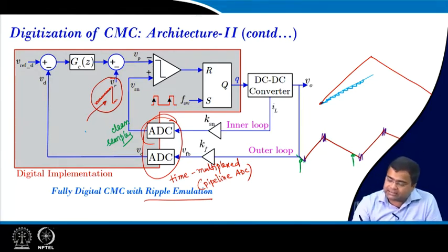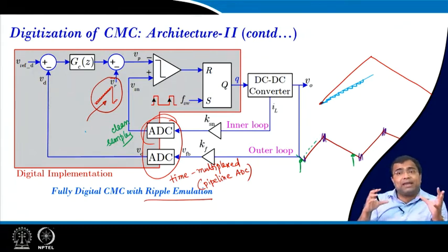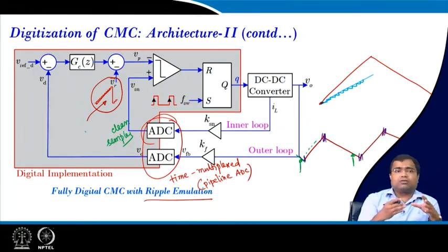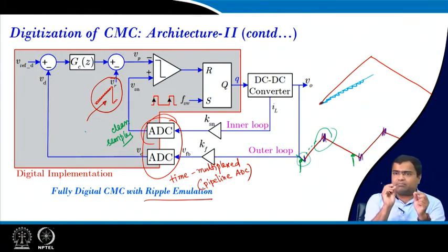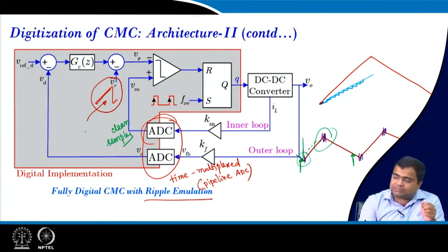So, as if you are adding a ramp here. By that way you can actually make the current controller or current loop insensitive to switching noise, and that is not avoidable in analog control. As a result, in most analog control, even for this case also, sometimes they use a minimum dead time, because if there is a large spike in the current, particularly during transient or some spike, we need to avoid it.